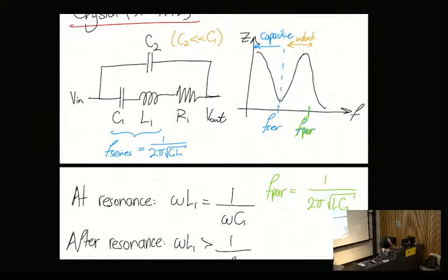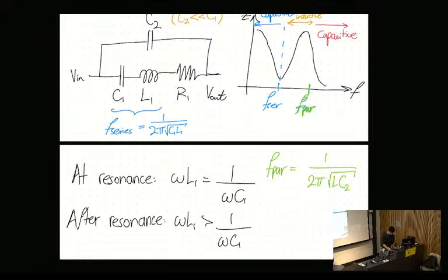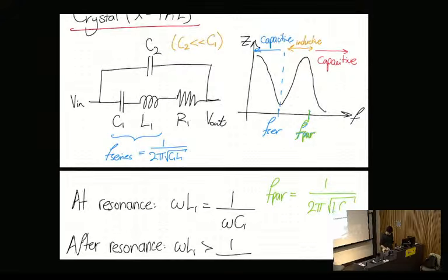No, that's not correct. Oh no, actually it is. That becomes capacitive. So the parallel capacitance then dominates, because this was a case of series resonance, the inductor dominates, but in parallel resonance, the capacitor dominates, which leads us to this sort of impedance behavior as some other resonance. So every crystal generates two resonances, a series resonance and a parallel resonance.